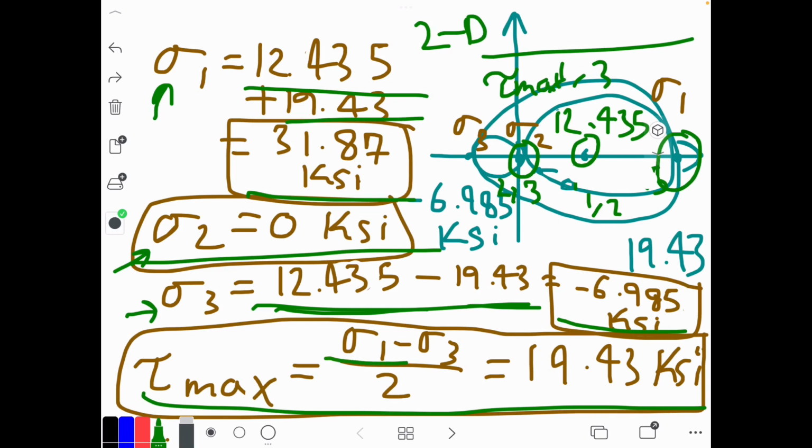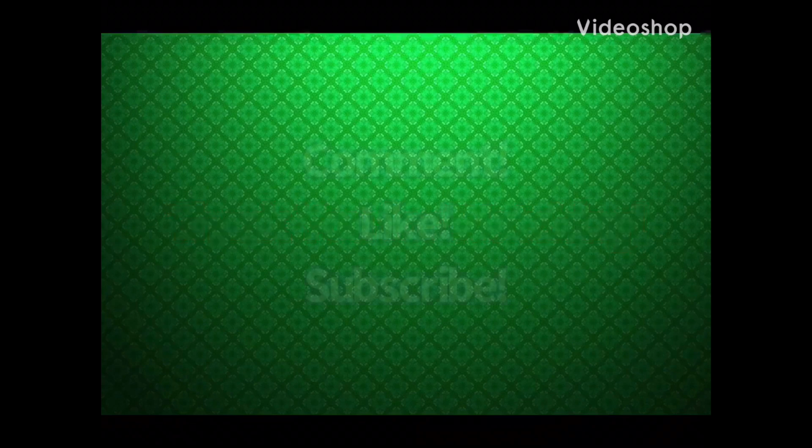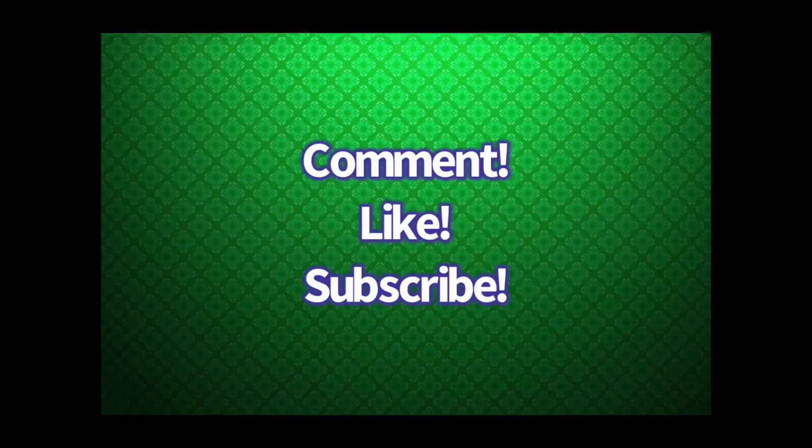So we take sigma 1 minus sigma 3 divided by 2: 31.87 plus 6.985, divided by 2. It gives you 19.43 ksi. Ironically, we just got the radius. So based on our calculation, the maximum shear stress is equal to the radius of the circle that we have.